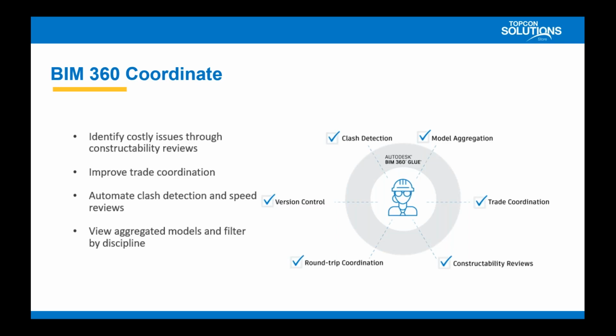We're also assigning those tasks of the clashes, so we can assign them to a certain individual or team, so they can take those away and we can focus those reports to those teams. It does a tremendous job at this. It takes an 8-hour coordination meeting where we would focus most of the time on clash detection, and pares that down to where we're only talking about big clashes that haven't been resolved during the week.